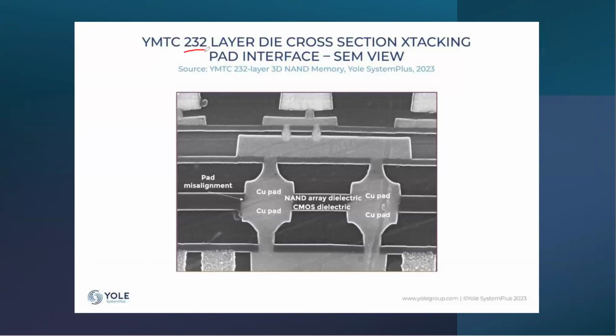And this one shocked the world, because that's barely below what Samsung can do. They use a copper bond and bond two wafers together. Wow, very nice. Remember, the pad alignment is not large. We'll talk about pad misalignment later. The pad misalignment is critical for EM reliability. A little bit off is fine, and we need to see how much is misaligned. That would be bad for electromigration.